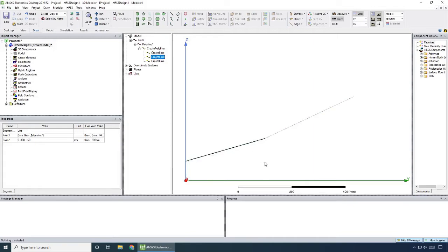Next, we can move on to this next segment. You can see that the first point has already been updated. So now we'll just look at the second point. We still want it to be flat, so the second, or the final point, which will be the z value, we still want that to be diameter over 2, but the y position, that is going to be determined by what the cylinder length is.